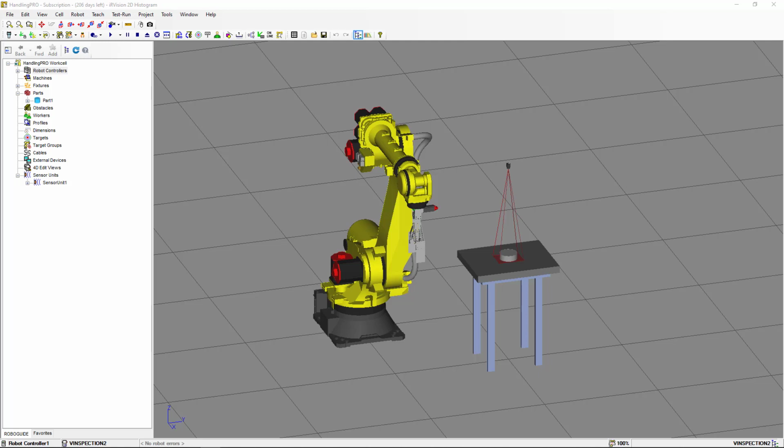In this video we're going to continue with iRVision inspection and we're going to look at the histogram tool. The histogram tool measures the brightness of an image, so this tool can be used in a variety of applications where the evaluation implies using the brightness of the measurement area. Since we're measuring the brightness of the image, when performing an inspection you need to be extra careful about the layout of the camera and the lighting.